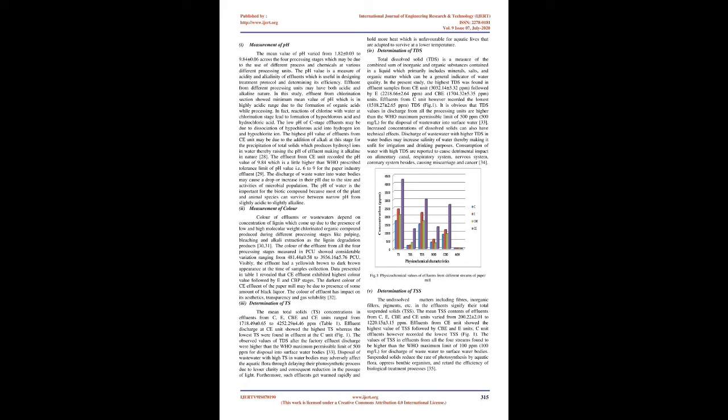A. Physicochemical characteristics of effluents. The agro-based paper mill under study produces a variety of writing and printing paper using bagasse, wheat straw, and other agricultural residue as a primary raw material. The effluent samples collected from various processing units of the mill were subjected to physicochemical characterization for parameters such as pH, color, TS, TDS, TSS, turbidity, BOD, COD, and AOX as per standard methods. The mean values and standard deviation of studied physicochemical parameters of the paper mill effluents are presented in Table 1.